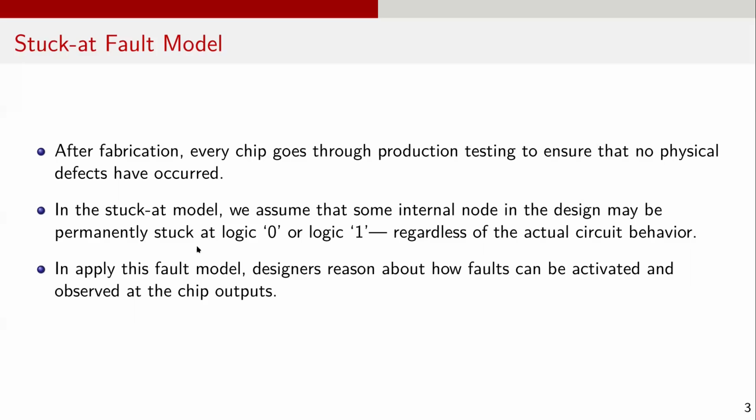To make this practical, simplified fault models are often used, and one of the most common is the stuck-at model. In the stuck-at model, we assume that some internal node in the design may be permanently stuck to logic 0 or logic 1, regardless of the actual circuit behavior.